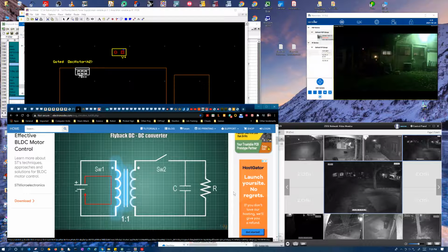Then, in a very fast instant, we open switch 1 and we close switch 2. Now the magnetic field that built up will collapse and the current will now flow towards the dot of the secondary coil. So voltage drop will be created in this way.